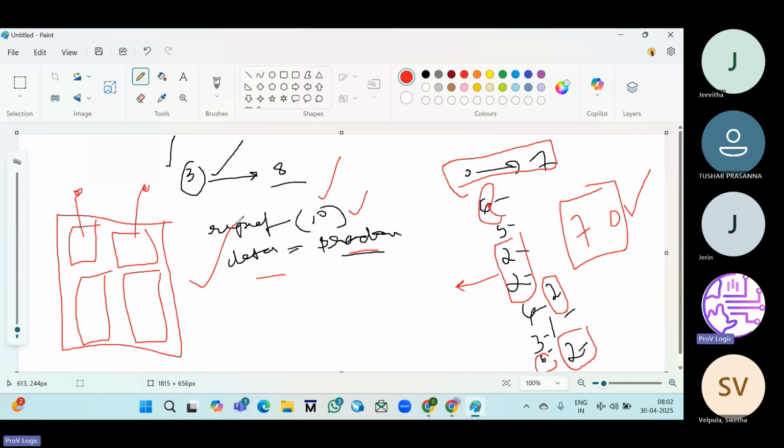If you want to make any changes to the test bench, we can make the changes at runtime if it is dynamic in nature. But if it is static in nature, we cannot change at runtime. If you can't, what happens? Suppose a test is running for 1 week, and meanwhile we need to make some modifications to the test. After making those modifications, you need to terminate the test and run again.